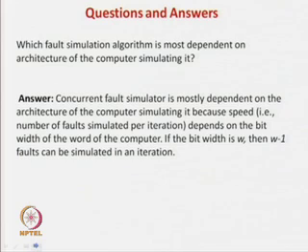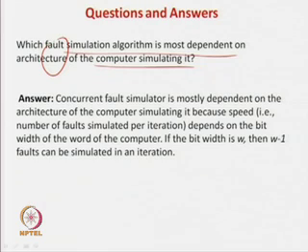Second question is, among all the 4 fault simulation algorithms which you have seen, serial, parallel, deductive and concurrent, which depends mainly on the computer architecture? Among them, only parallel fault simulation is dependent on architecture because to each net you assign an array and the length of the array is processed in parallel. So, you have to think about bit parallelism. If your computer has 32-bit parallelism, you can have a maximum 32-bit array in all the inputs.